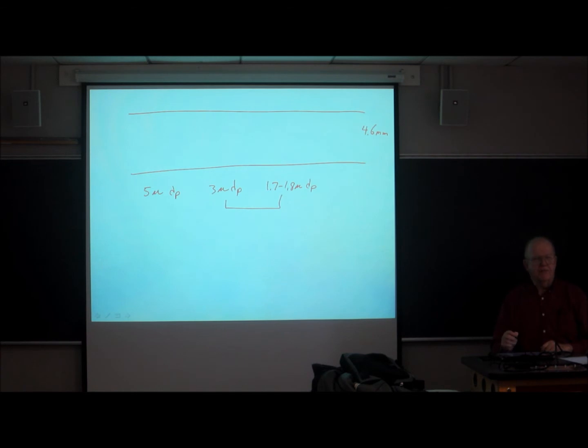When this sub-2 micron barrier was breached, 400 bar, 5,000 psi just didn't cut the mustard. It simply wasn't enough to operate the column properly. And a number of companies started to introduce very high pressure systems on the order of 800 bar, then 1,000 bar, then 1,200 bar, and I think currently 1,200 bar is the maximum that's available.